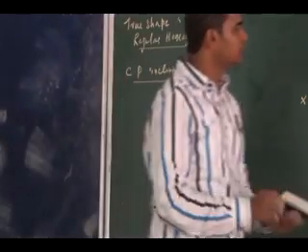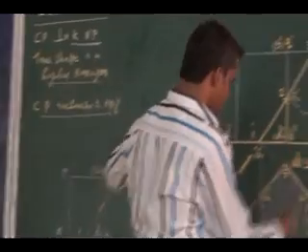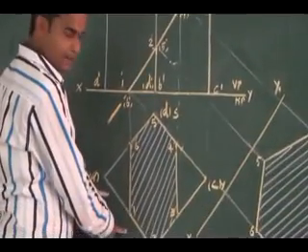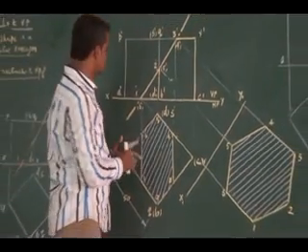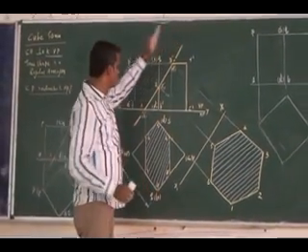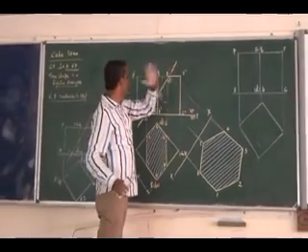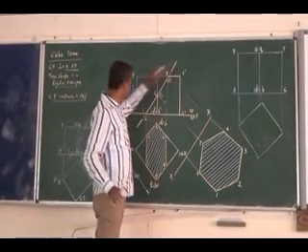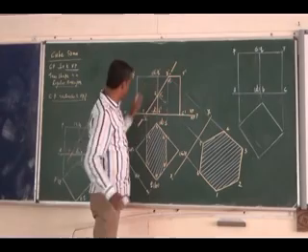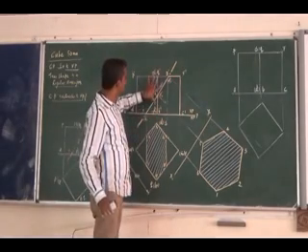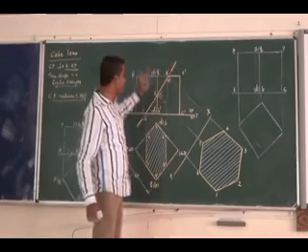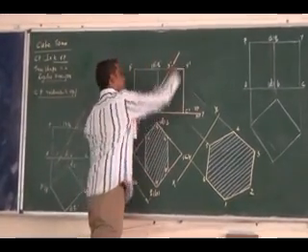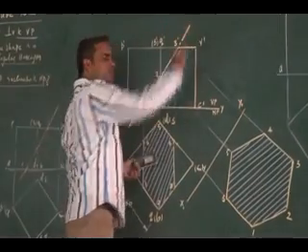You can see here, this is the top view I have drawn. Then front view. And as you know, since it should give me 6 cutting points, and the cutting plane is perpendicular to VP, I have to represent the cutting plane here. And the cutting plane should pass through the middle of this side and middle of this vertical edge, and it should pass through the middle of this. Then only I will get a regular hexagon as a true shape. Then I have represented the cutting plane passing through these middles.